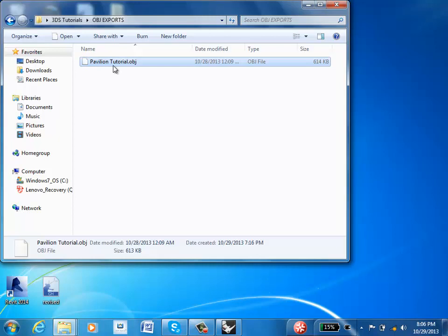There's a little checkbox, just make sure that is unselected. It'll say convert XY to YZ or something like that, just make sure that that is unselected. If you do have that selected, obviously your model will come in sideways in your 3ds Max, and that should be a cue that you've done it the wrong way or that you left that box checked.